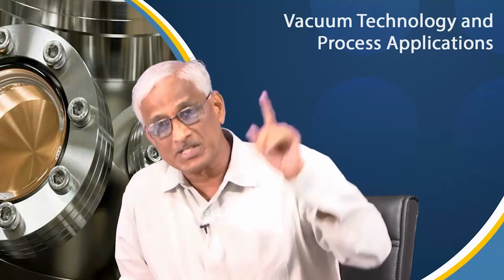It is not just that I want 10 power minus 10 torr, so I use this ultra high vacuum pump, because the chamber was starting from atmosphere. Initially, these pumps are not useful for that 1000 millibar to 10 power minus 3; you use some other pumps. But the selection of that pump should be a dry pump, because at 10 power minus 3, these high vacuum pumps are going to take over, because normal pumps cannot pump below that. So, while taking over, it demands good quality.